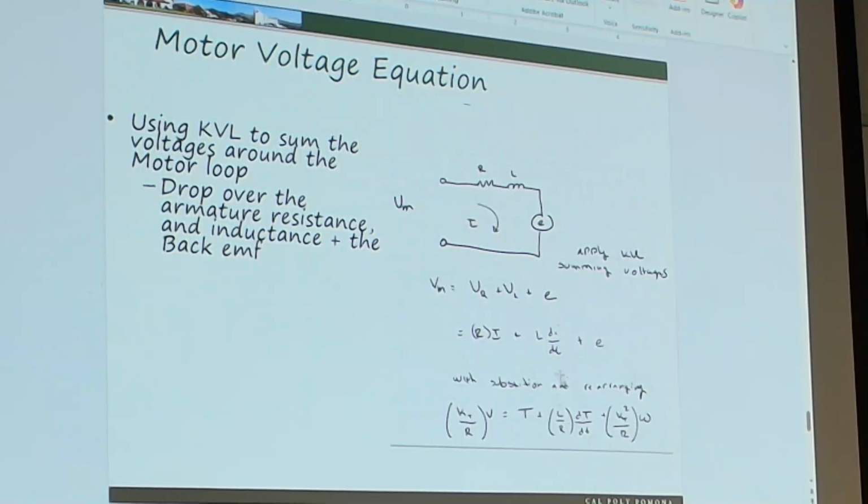So here's that torque. Current and torque go hand in hand. That's the one thing I'm trying to get across. But I can look at some kind of coefficient with this term called KT, which is going to be my torque coefficient of my motor. Basically, that comes out of the efficiency between that motor power, so PE to PM. It's really going to be captured through this coefficient, oftentimes known as KT. Everybody with me so far?